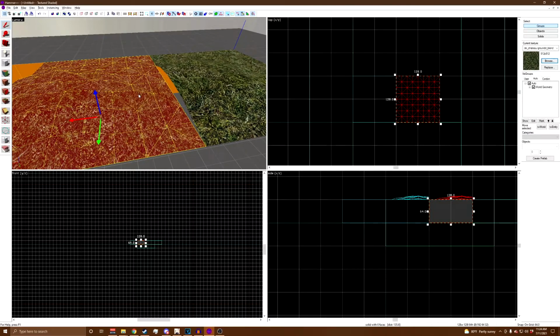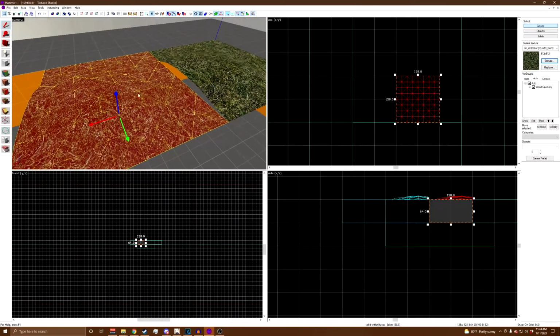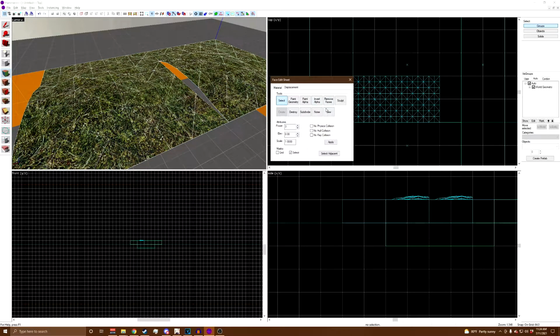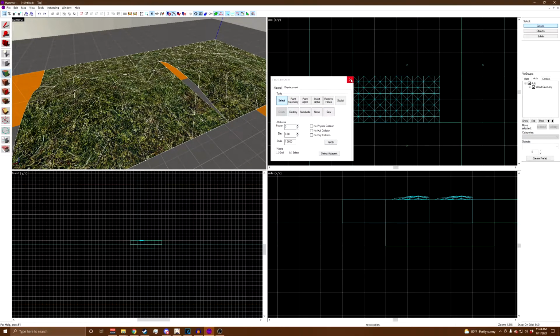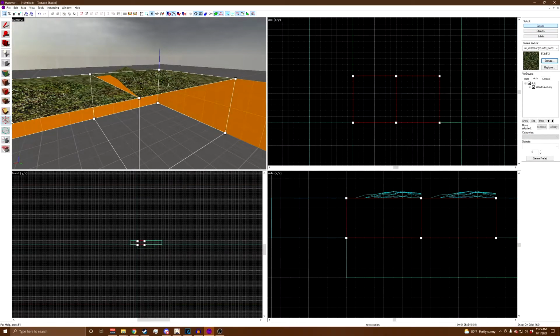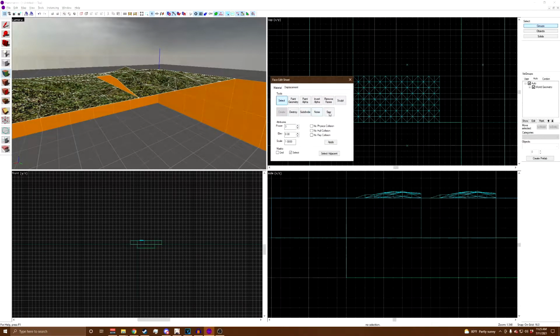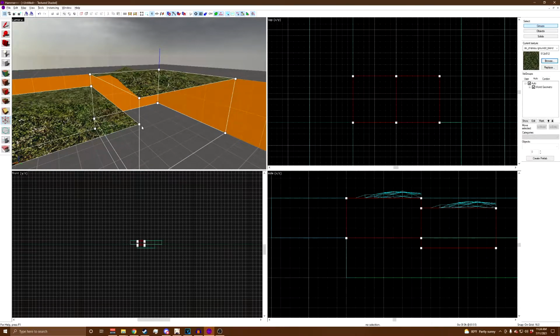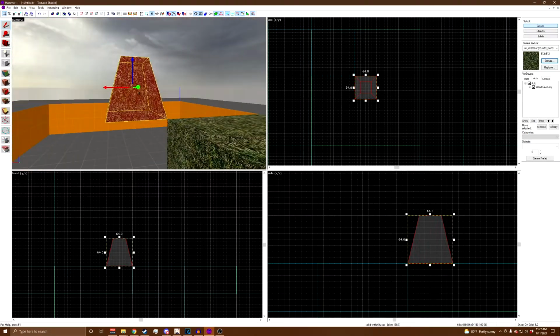2 different displacements can be sewn together, so long as the vertice coordinates for the 2 displacements match with each other. When you sew 2 displacements together, it will connect any gaps between the sculpting of the 2 displacements. This is an extremely useful tool, and you want to make sure that your displacements can work with it whenever possible. As you can see here, these 2 displacements are sewable because the vertices on their adjacent sides share the same exact coordinates. When I move this displacement downwards, however, they no longer exist in the same space, therefore cannot be sewn together. 4th rule, but it's also kind of a suggestion.